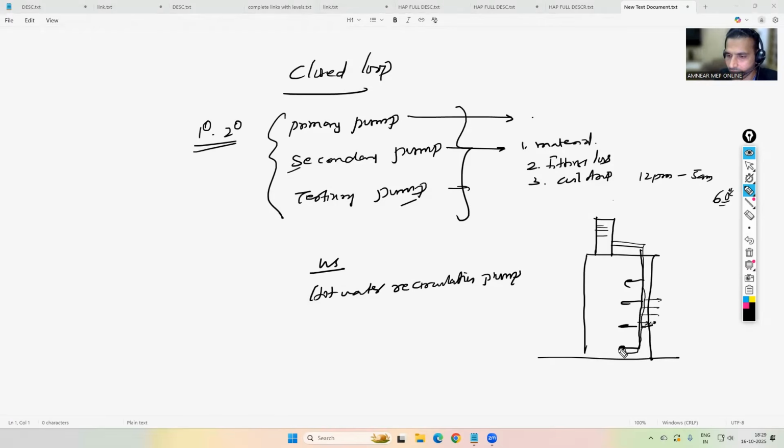So in the early morning, when the people are using the water, up to this point the pipe will be carrying a volume of water. All that volume of water has to flow away, then only people will start getting the hot water. This scenario has to be avoided. We have to make sure that always within the building we will be getting continuous hot water supply.